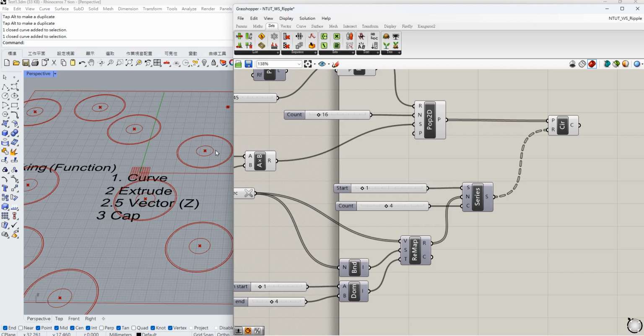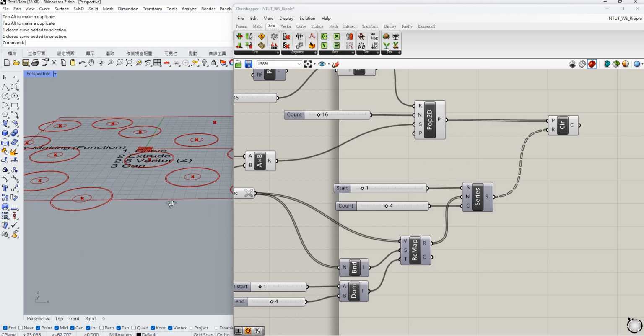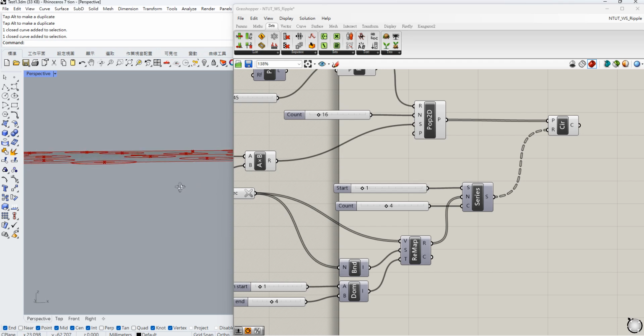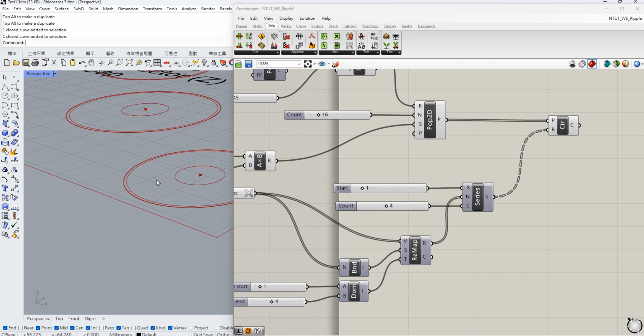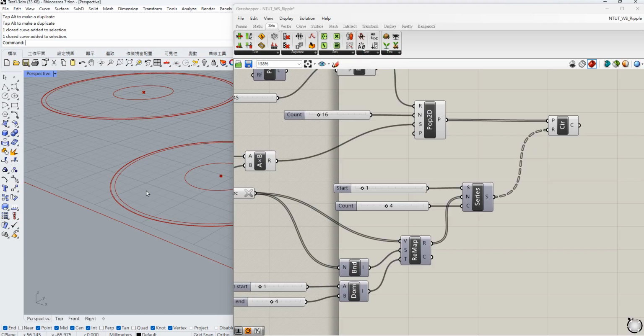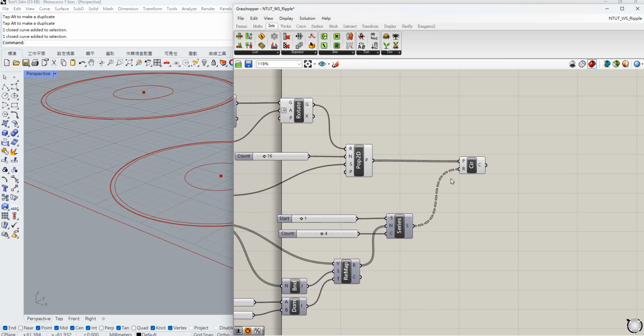The next thing is that right now, if you rotate your view to probably a side view or something, you will find out that everything you did is flattened. There will be a problem in that. Right now, all these things are just lines. So in order to see them in the render view, or make them a real, true 3D model, we have to make them become surfaces.